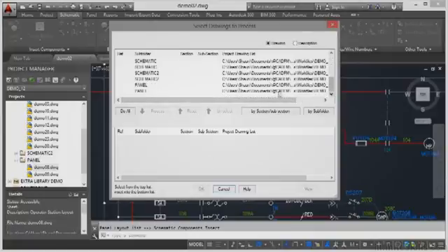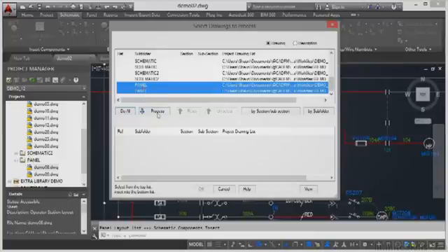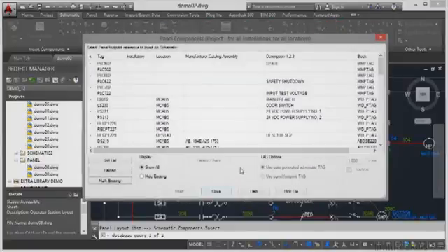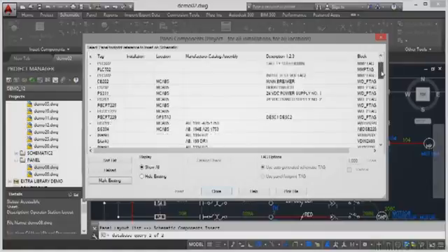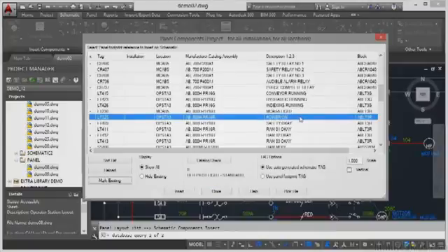If I scroll down this list and look in the subfolder column, there's a panel drawing, and also there's another panel drawing. Holding down Control, I select those two. I then click on the Process button. It lists the two drawings that are going to be processed, and I click on OK. That then gives me a panel components list available for my schematic components drawings. Now you'll notice there's a block column. So if I slide down here using the slider, there's my ABLT3R, and there's my power on light there.